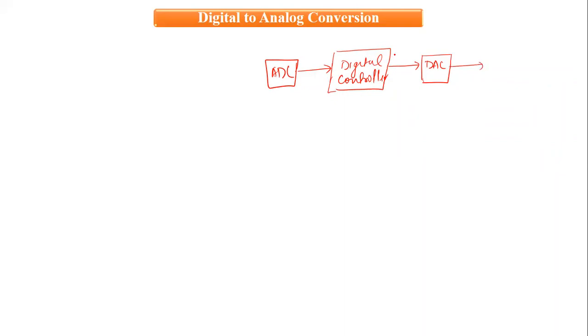So here we get the control output which is denoted by u(k), where k is the sample index. So from the D to A converter we get some analog representation of this particular control signal. It is given to the final control element, and then we have the plant.